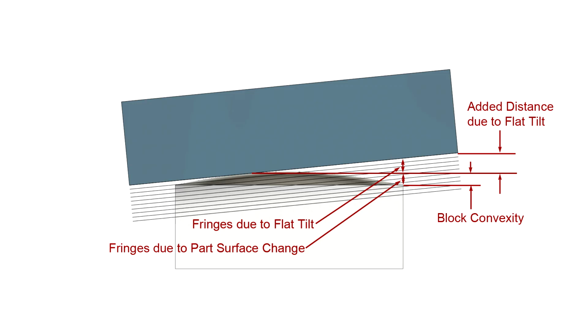The bad news is that it's usually difficult to position an optical flat accurately parallel to a part's surface. The good news is that we typically don't want the flat parallel, and the tilt provides very useful information, but that's getting just a bit ahead of our story.